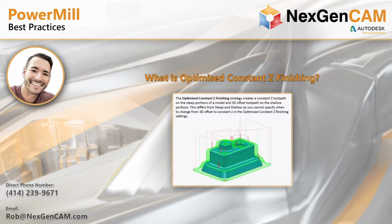The only difference is that with optimized constant Z, you cannot specify when to change from 3D offset to constant Z. Inside of the steep and shallow finishing toolpath settings, there are options to define when you want PowerMill to go from 3D offset to constant Z. There's a transition point, called the threshold angle, as well as an overlap you can set. So optimized constant Z is a good toolpath, but there are a little bit more features inside the steep and shallow strategy.